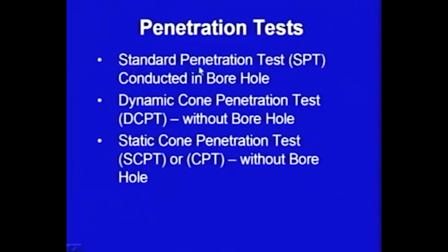under this category we will be discussing the standard penetration test, SPT is the short form, and this test is conducted in a borehole. A borehole is needed for this test and we take the sample also. So, you can get the sample of the soil and you get field test results.